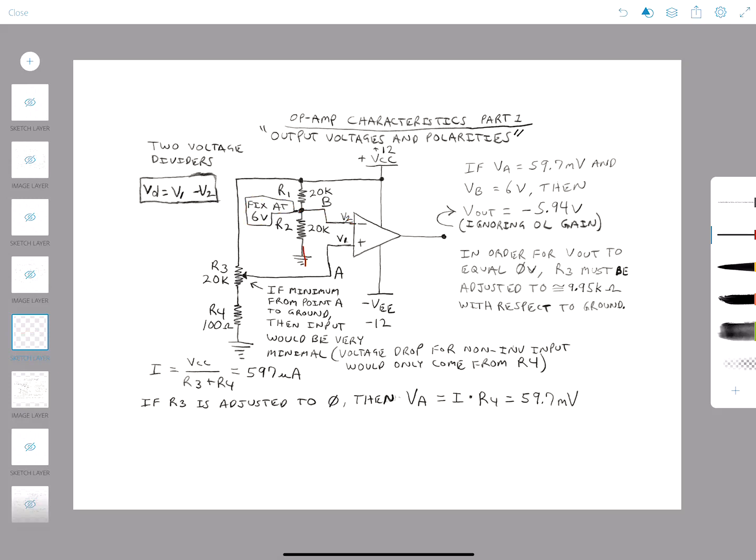well, let's look at current flow first. So current flows from negative to positive, so we have current flowing this way, back up to our positive 12 volts. And now we know where this comes from. If both of these resistors are exactly the same value, we automatically can say that each one has 6 volts across them. So we have our 6 volts right here in the center. So no calculations needed for this, pretty straightforward. So we have 6 volts sitting on our inverting input.